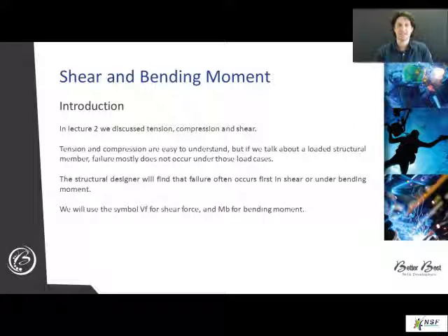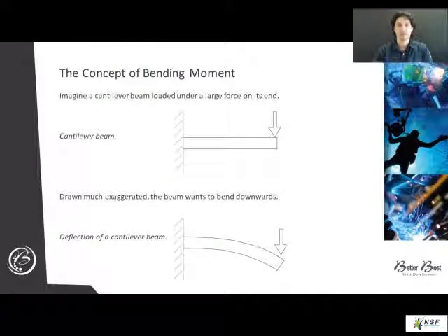As discussed previously, tension is the force of stretching an object apart. Similarly, compression is the force of pushing an object or objects together. Tension and compression are easy to understand, but if we talk about a loaded structural member, failure mostly does not occur under these loads. The structural designer will find that failure often occurs in shear or under bending moments. Shear force is a sliding force and acts perpendicularly to the body.